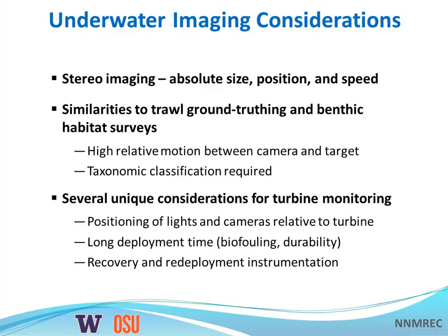Uniquely for turbine monitoring, we have to think about how the lights and cameras are positioned relative to the turbine to provide imaging of the turbine without interfering with the inflow to the turbine rotor. Deployment times are much longer, on the order of months. And as a consequence of this, there has to be some mechanism to recover and redeploy the instrumentation. As I mentioned previously, we're in 60 meters of water here, so this has to be done without the use of divers. Next slide.